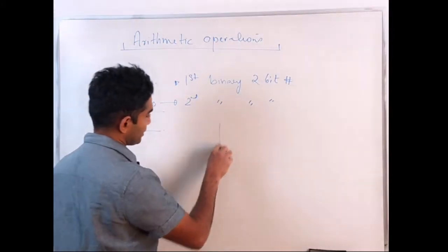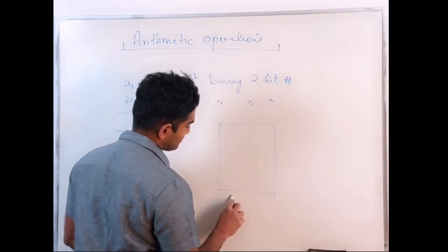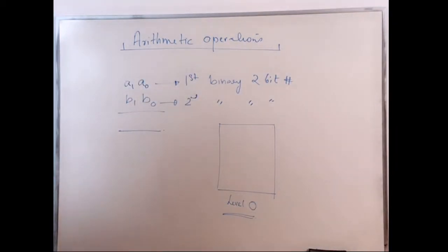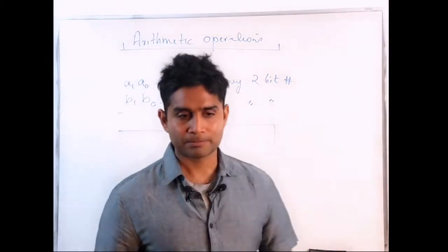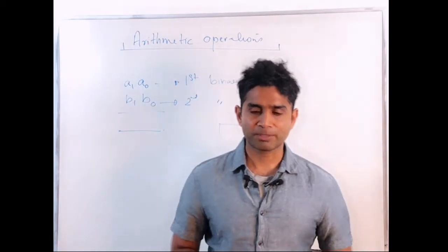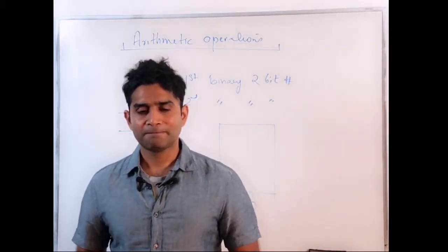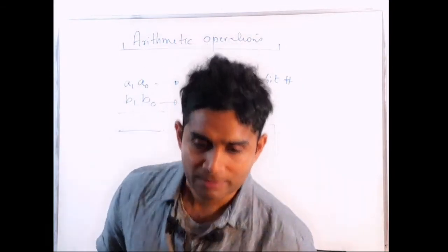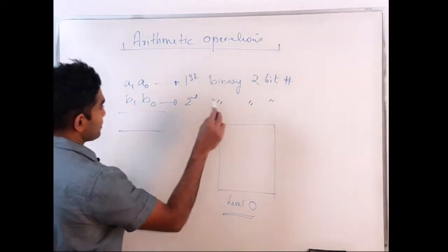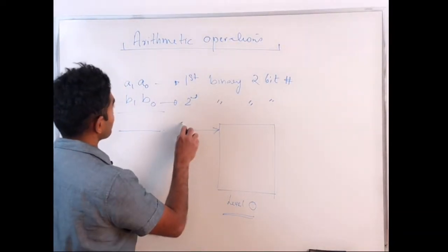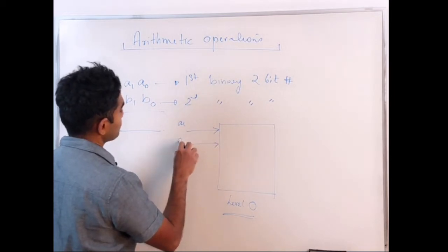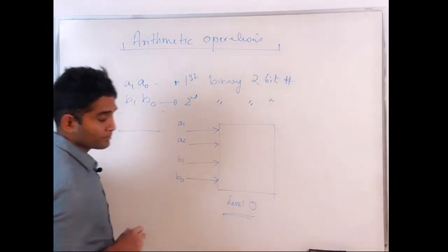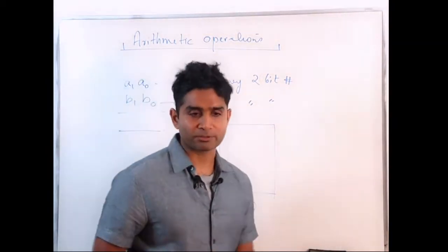Again, I'll put down that information in the form of a level 0 diagram. And how many inputs do I have here? For this particular circuit, how many inputs do I have? A circuit that would add 2-bit binary numbers together. I have 4 inputs. Perfect. So those inputs are A1, A0, B1, B0. Right? How many outputs would I have for this particular circuit?